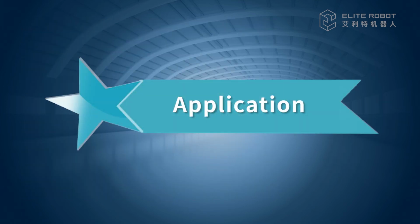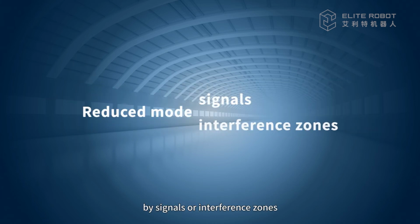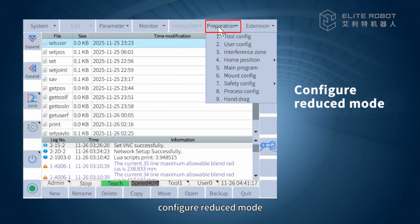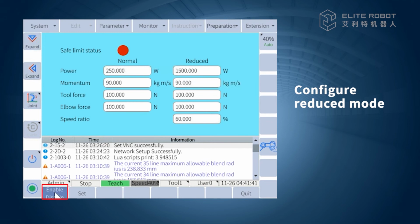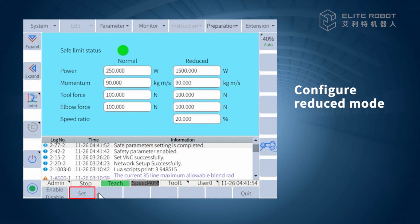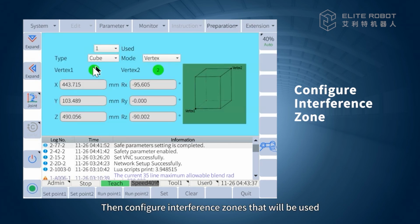Application. Reduced mode can be activated by signals or interference zones. Take reduced mode by user PLC and interference zones as an example. First, configure reduced mode. Then configure interference zones that will be used.